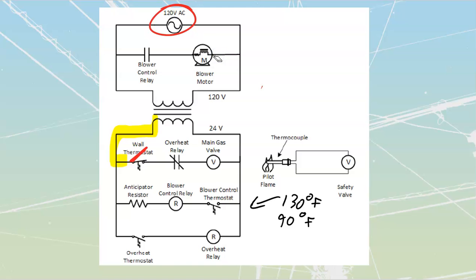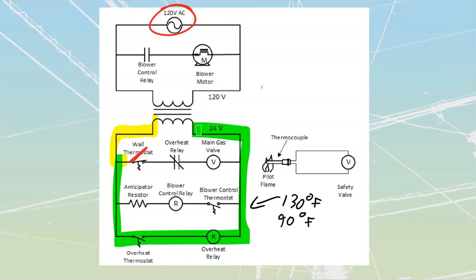The blower is then going to shut off at that point. The last section that we haven't talked about was just this rung over here, which is going to be for my overheat thermostat. All that my overheat thermostat does is prevent me from getting to too hot and dangerous of a condition inside of here.